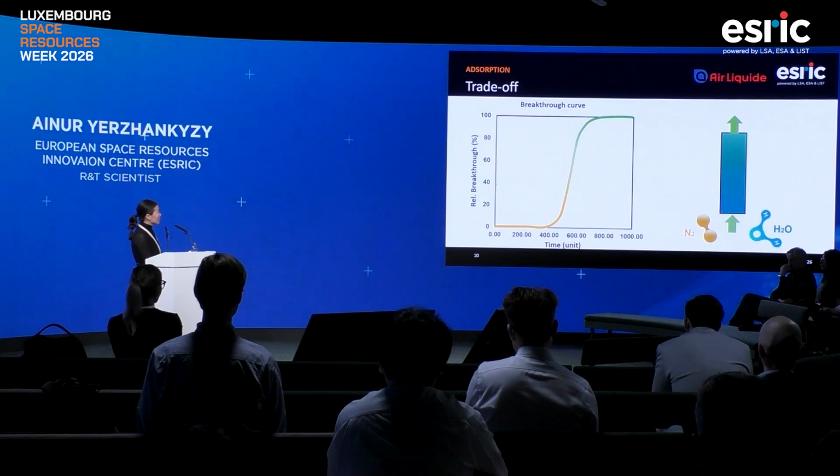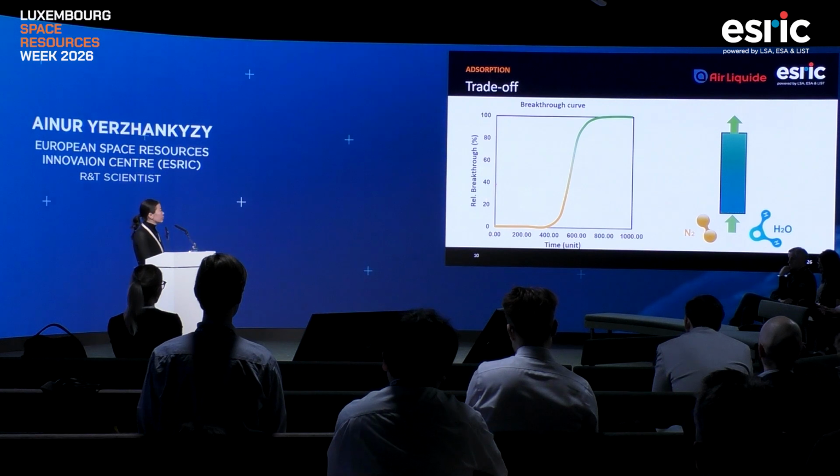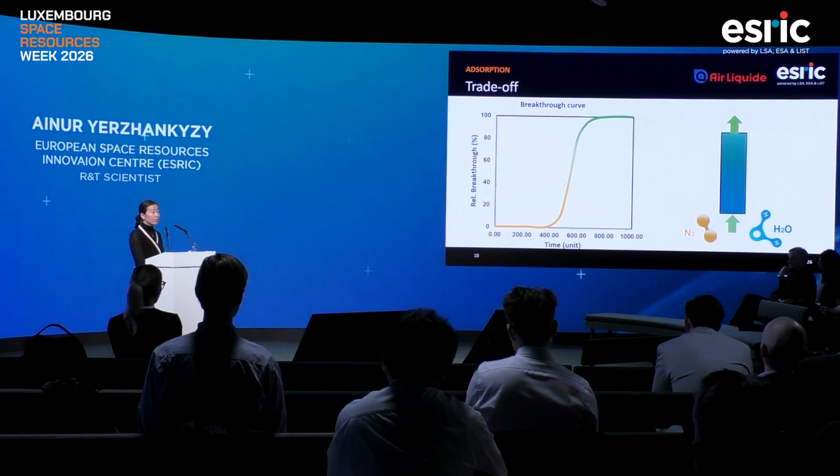So with this curve, I just wanted to say that an adsorption system could be flexible in deciding when you want to stop your adsorption step. Either you want to stop before you start losing any water molecules, or you want to make sure you adsorb as much water as you can, so your column will be mostly filled by water. By doing that, we could play with the purity and recovery of the product.